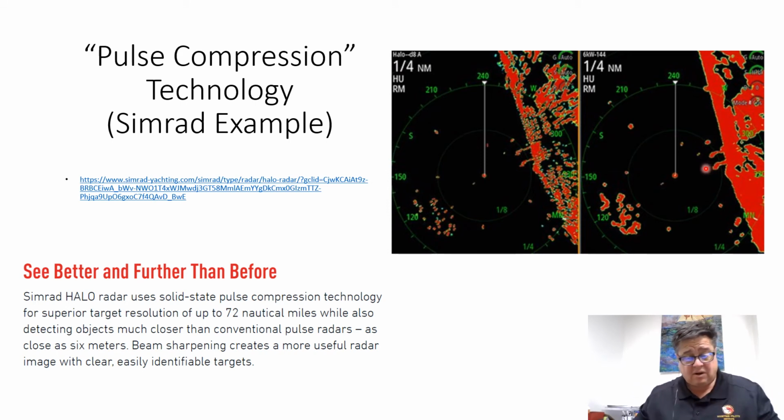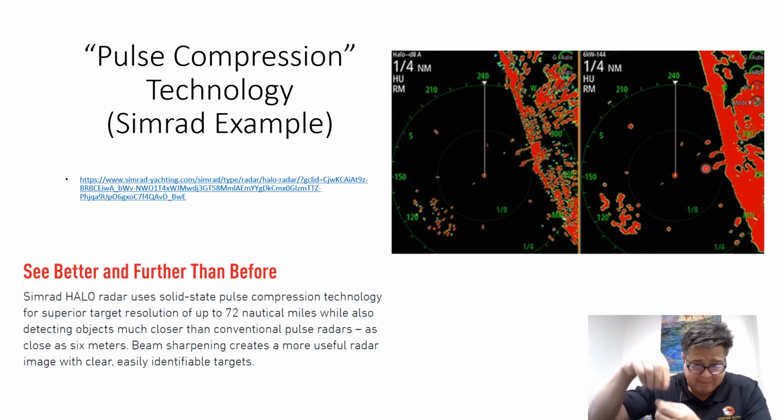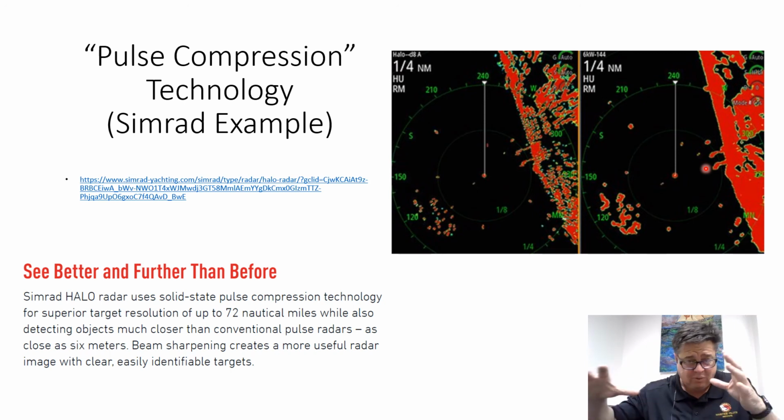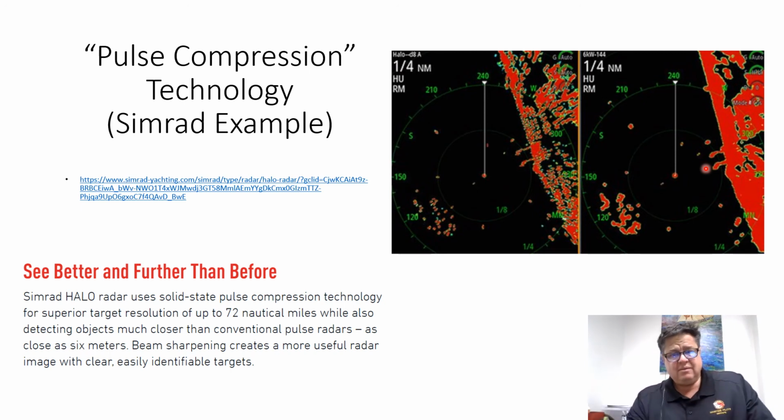But I saw a 1.5 centimeter, not a 3, but a 1.5 centimeter pulse compression technology HD radar that was able to see every pole in the yacht basin. It could see the mooring lines go into the vessels that were in a yacht basin. It could see birds that were sitting on top of poles. You'd see the pole would look different because it had a big bird on it. And it was amazing. I thought much better picture, excellent for low range.